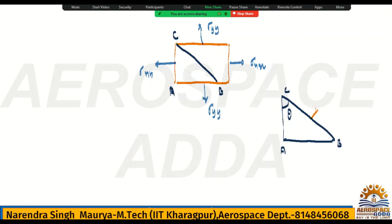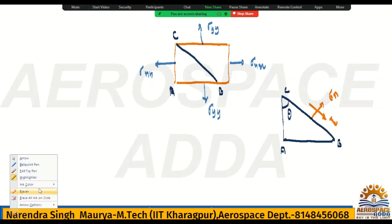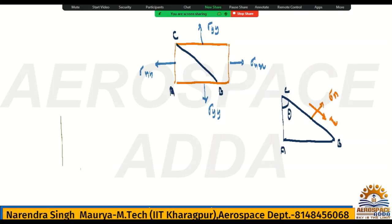So I must say this normal stress over this inclined plane will be sigma n, and obviously somewhere you will have shear stress on this plane. So shear stress will be here tau. In z direction thickness is negligible. You forget about z, only x and y. If you talk about x and y, then I will show how this oblique plane will appear. Z is just a hypothetical assumption. For any thin section you talk only about the xy plane. So now in the xy plane, this is the oblique plane here. This oblique plane will appear like this.